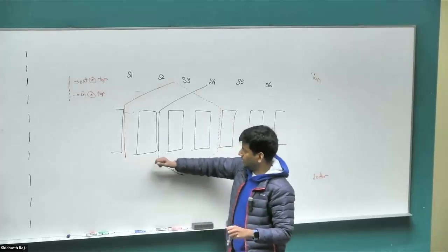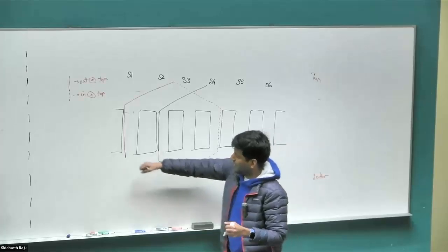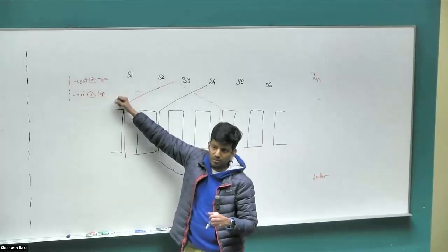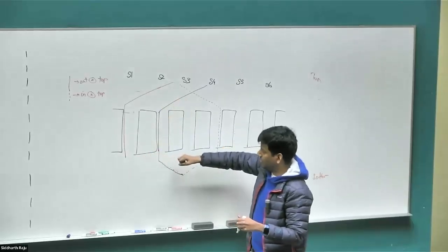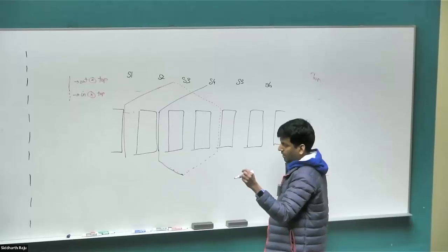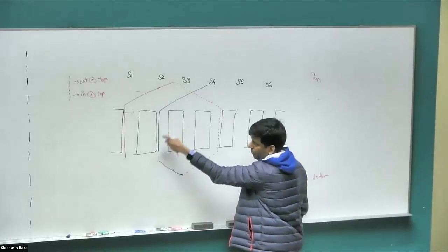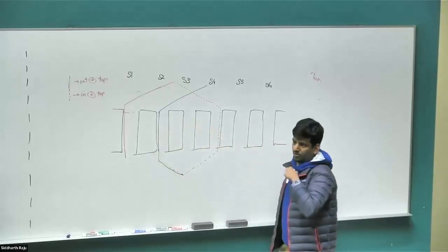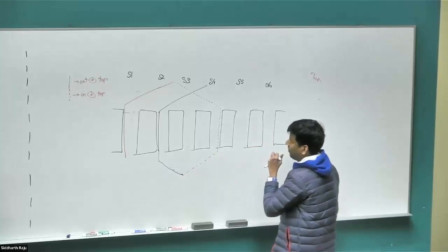Right? So this is what the progressive in progressive winding means. Going from slot 1 to slot 2. There is another way I could have wound it. Instead of going from here, I could have taken it to slot 6. That would be called retrogressive winding. So there are different ways in which we can wind it. And going to Ben, your question, if I instead took it to slot 3 here instead of slot 2, that would be a duplex winding. Once I draw the commutator, you'll see what the trouble with that structure would be.